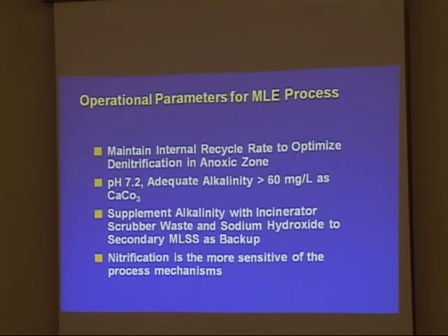You want to maintain your internal recycle rate to optimize denitrification. You don't want it too high if you're going to be introducing DO. If you start introducing DO, the two things you're going to immediately look at is, do I have too high of a DO at the end of my aeration tank that I'm returning? I can taper that off. Or is there a precipitation event going on and I've got diluted, very cold, but highly oxygenated primary effluent coming in that could be causing a problem.